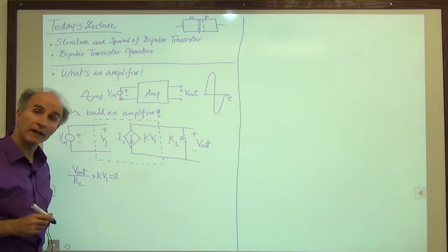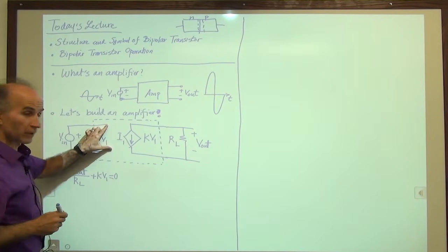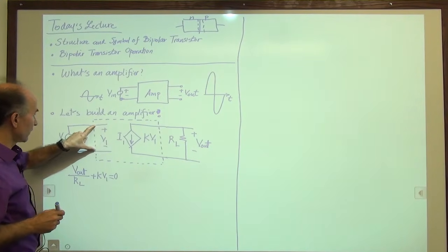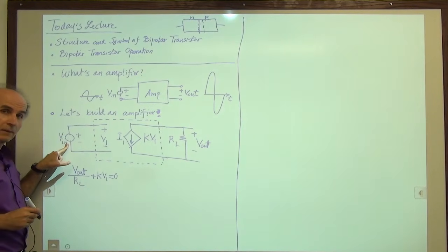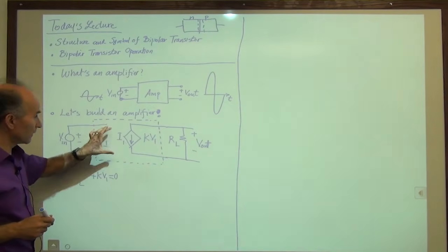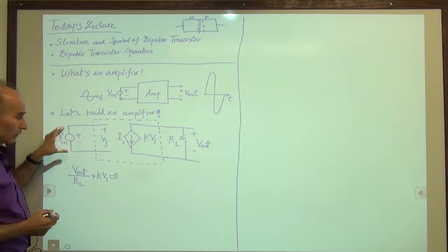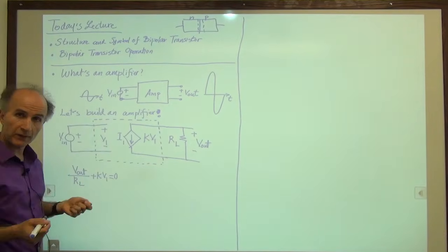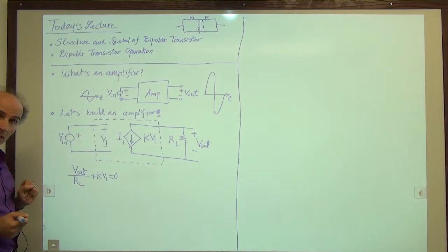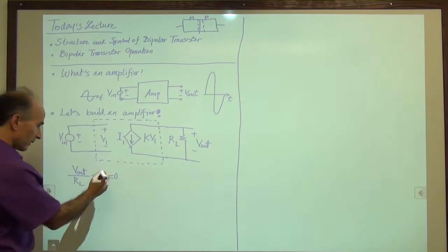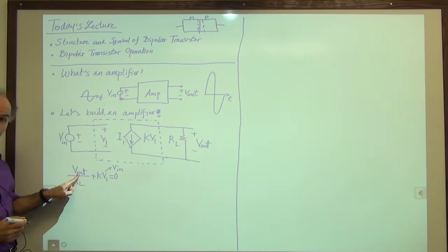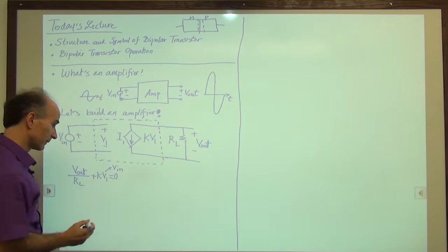Now, do we know how much V1 is? V1 is this voltage that is inside the device. But all we've done is we just connected two wires to the input. And because the wires are ideal wires and there's no current anyway, this voltage must be equal to this voltage, right? It's just like you took a battery and connected two wires to it, so you should still measure the battery voltage. So V1 is actually the same as V in. So let's replace V1 with V in, and let's try to find V out, because we are interested in the output voltage.